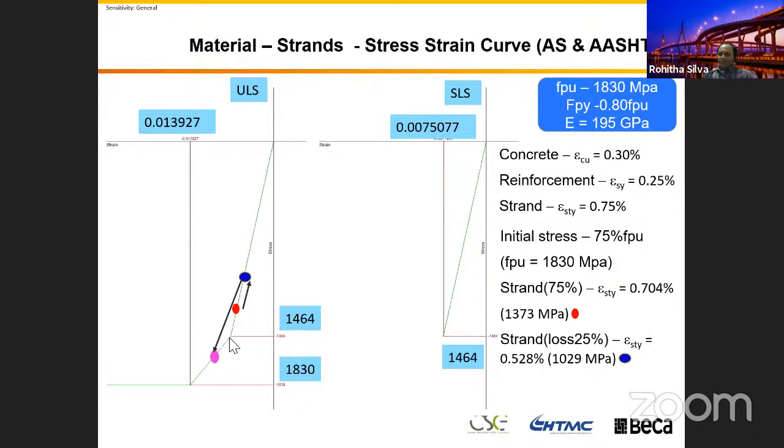And then from there, from 0.8 to the breaking stress, you got a different gradient, it's much more flat. And then after that, flat. You can increase your strain, but your strength won't increase. But we never design our structures in this area. This is what is important for you to understand.